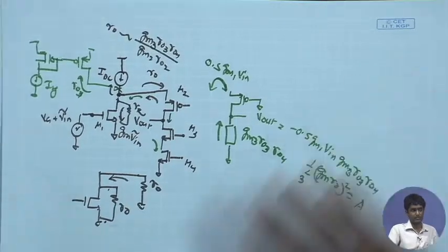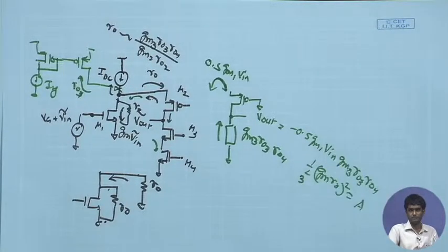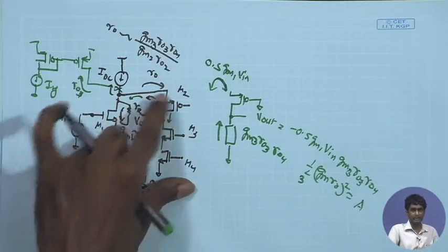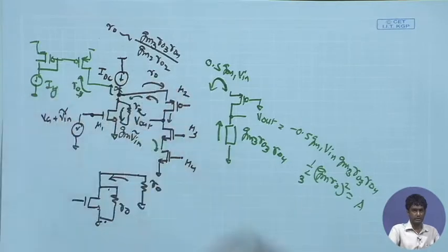Sir, here we need the gate voltage of the first NMOS also defined, otherwise. Sorry? Voltage of the first NMOS. Drain voltage. Yes, because it is going to the PMOS source, so if it is small, then there will be a problem. No, that has to be defined properly. So, of course, it has to be sufficiently high so that we are able to directly connect it to the PMOS source.